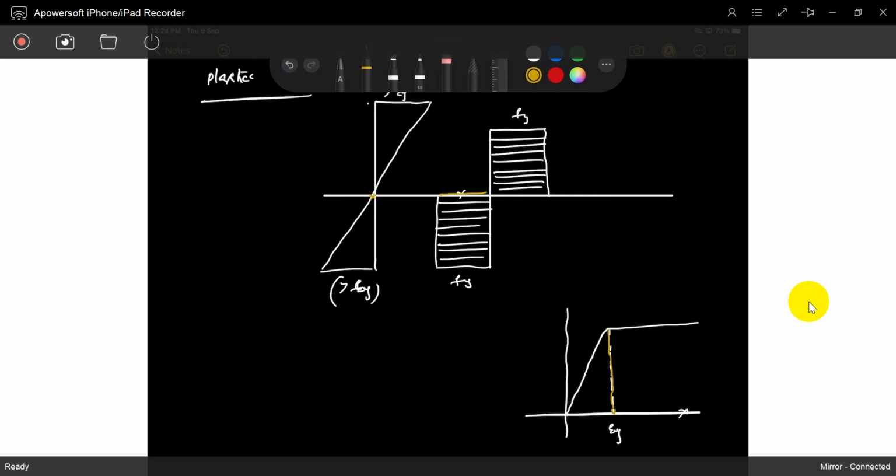So that's it. If you see, every fiber reaches the Fy. This is Fy. Every fiber reaches the Fy. So once the fiber or the point reaches the Fy, after that point there is no increment of the stress, but the strain is increasing. Sir, how does it increase automatically? Not automatically. If a very small load is applied, the strain increases very abruptly. That is the point.